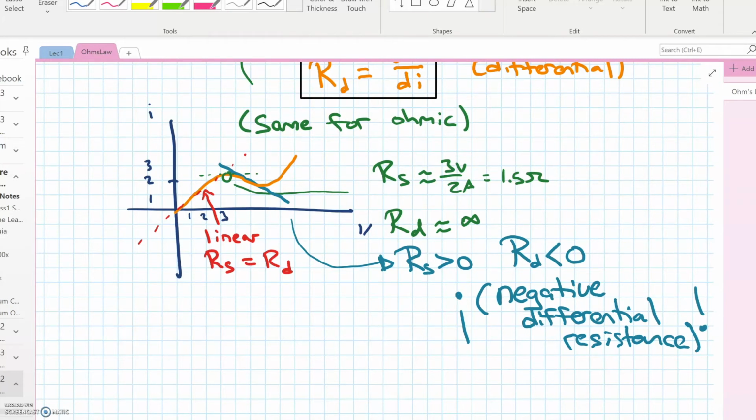For example, fluorescent lighting, when you first turn it on, you have a high voltage which kickstarts some current. But as soon as current starts flowing, all of a sudden you have far less resistance along the path. And therefore, if you just took one of these light bulbs and flipped on the voltage and left it on, the thing would explode. For this reason, there's something called ballasts that are in these lights, and they repeatedly switch directions of the current or turn it on and off.